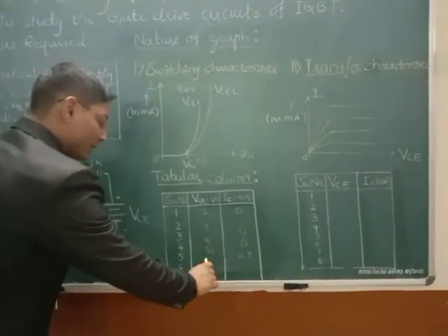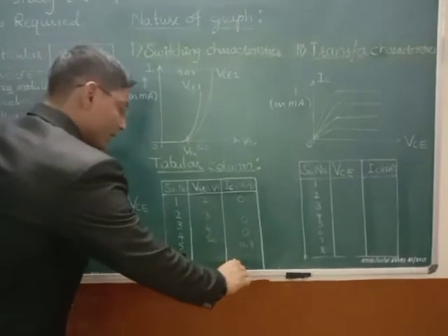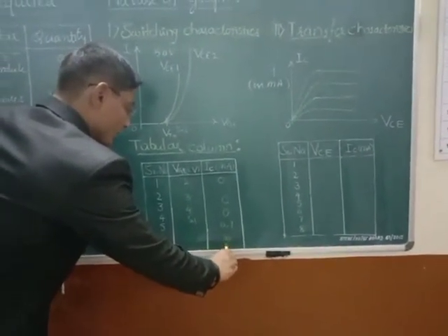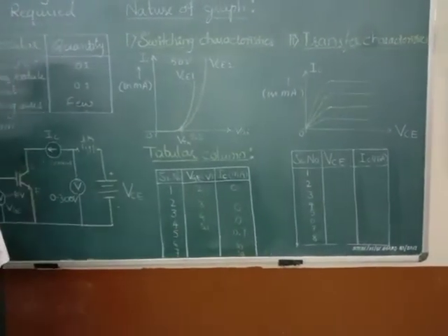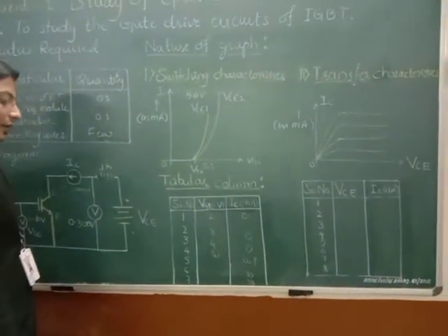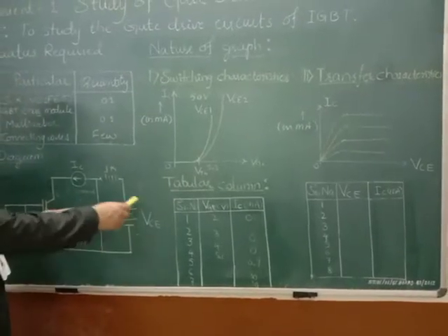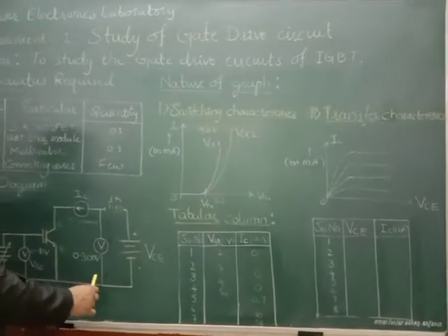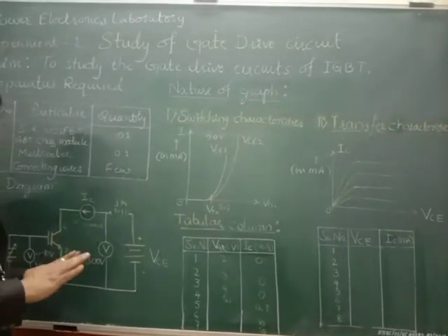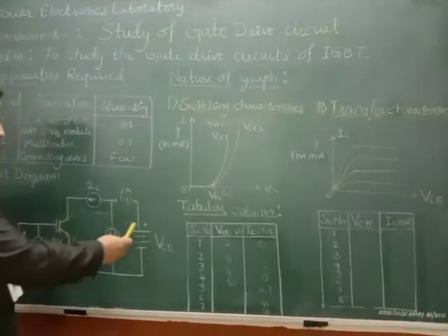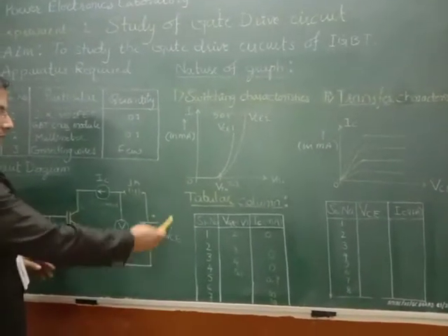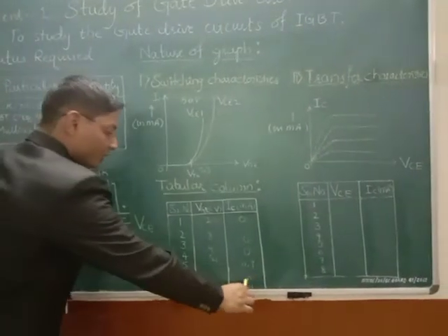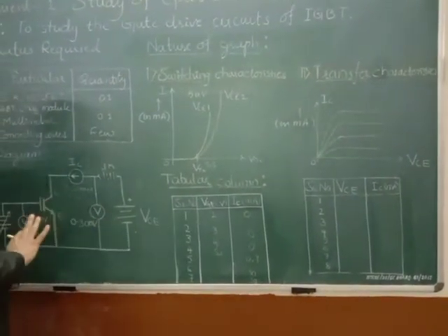After that, when we increase the voltage, the current is going to increase to around 30 milliampere, after which for every increase in the value, the current is going to remain constant. What that indicates is that for a particular applied VCE voltage, only a certain amount of current can flow. After that it will remain saturated, because the applied potential difference is sufficient only to make 30 milliampere of current flow through the circuit, not more than that.